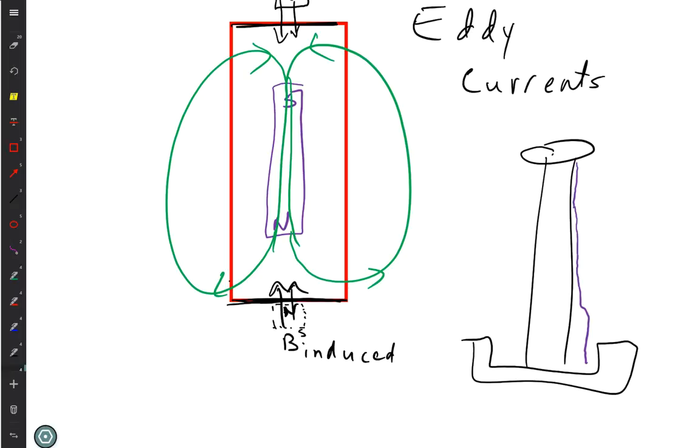Well, you would like to have electricity. And so in your Volt, you do have normal brakes, but before that activates, you press on the brake, and it's essentially doing this thing, except instead of letting the current go somewhere, you have it in a loop, and you use that current that's induced to charge the battery. And so cars like the Volt or a Saturn, when you brake, you're recharging the battery, getting back some of your energy. So cars like the Volt, the Saturn, the Prius, they get really, really good economy for city driving.